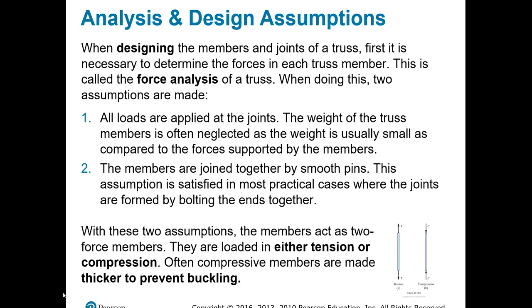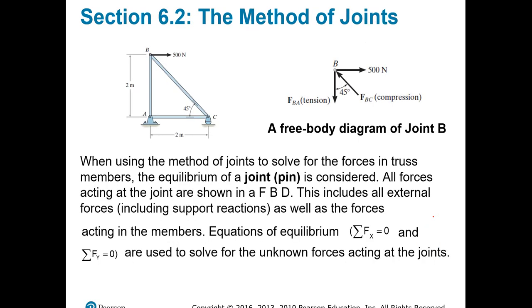So at the end of the day, you will have a bunch of members that are connected together through pins. What we do is study those pins. As we study them, each one of the members will be subjected to different loads, and those could be loads in tension or loads in compression, as you can see right here. Usually compressive members are made thicker to prevent buckling, but that's not part of statics right now, and you will have it in material science. So there are different methods to study these types of structures.